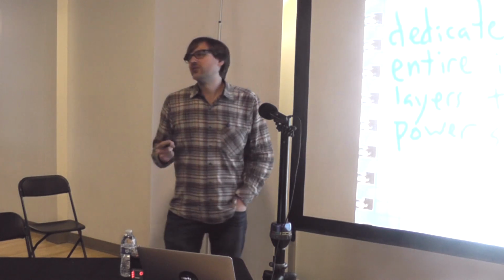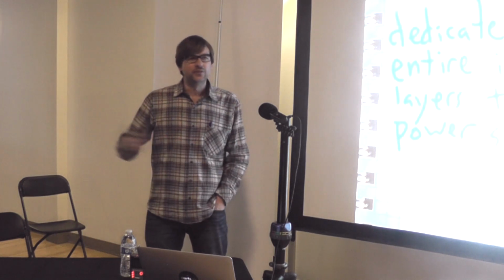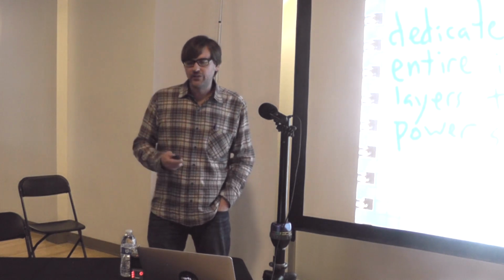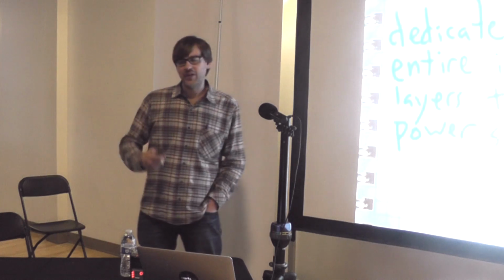And keep the RF signals on the top. Don't run them through vias. Don't do anything complicated with them. Make your RF signals as simple as possible, and we'll talk about that more later.